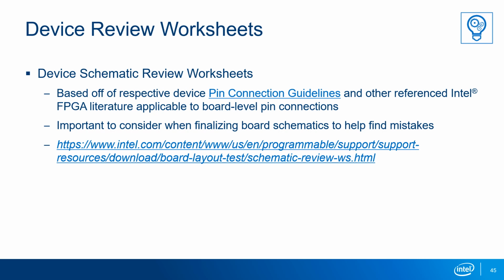Intel FPGA provides schematic review worksheets for each device family intended to help you find mistakes in your schematic and adhere to design guidelines. These worksheets are based off of the respective device pin connection guidelines and other reference literature applicable to board level pin connections that need to be considered when you finalize your schematic.